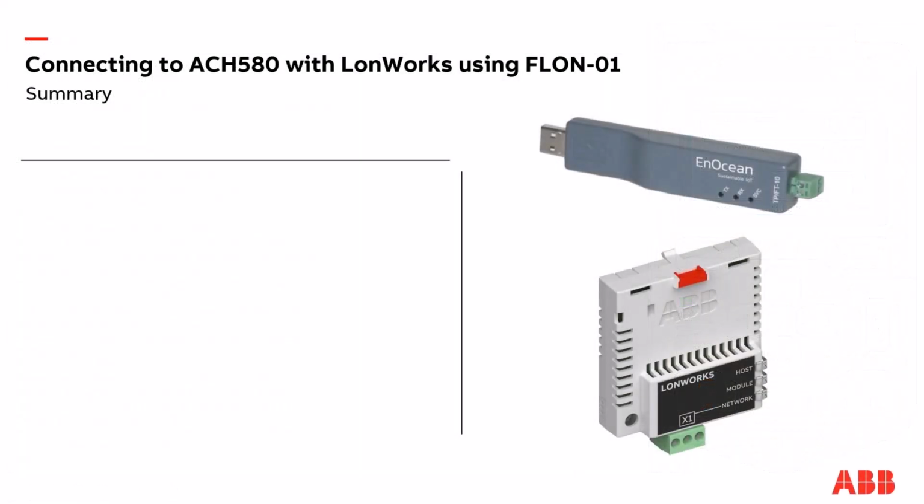So that concludes this presentation on how to connect to an ACH580 over Lonworks using the FLON module. And I'd just like to summarize the steps that we went through in this presentation. The first step in connecting to the Lonworks network was to acquire this USB to LON network adapter. And then to support its use on your laptop, we had to install this driver, which was necessary to support any applications that use the adapter for Lonworks.